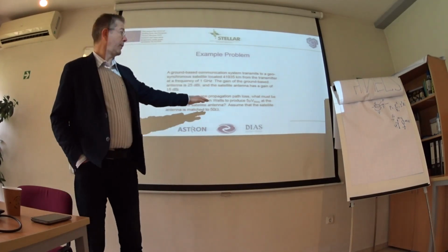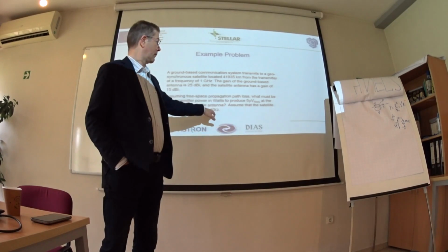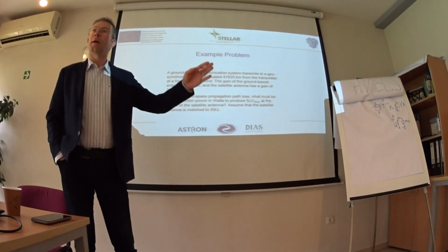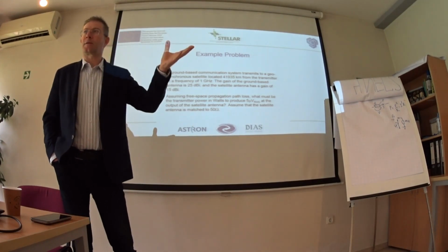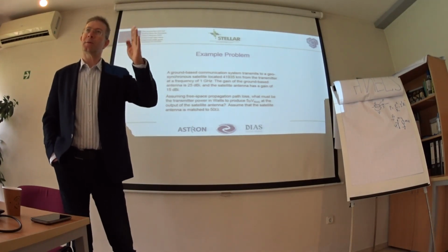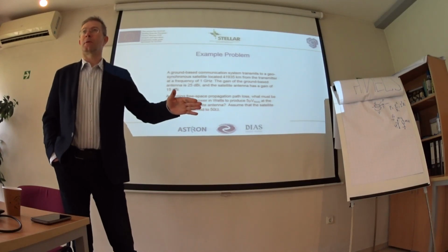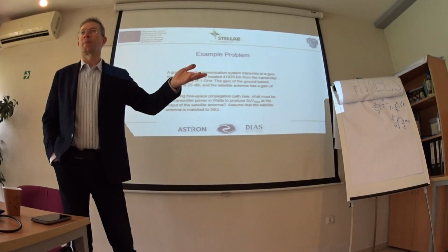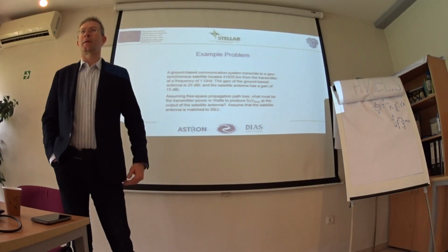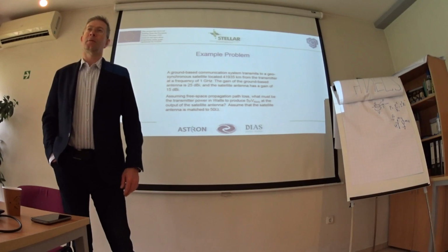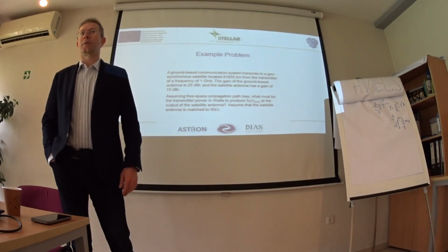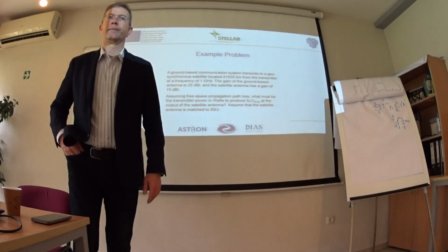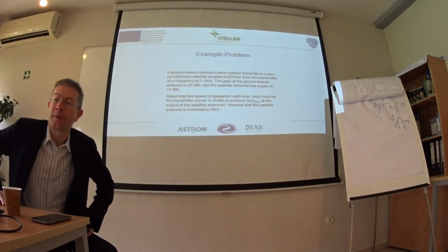And then we divide it by the impedance, 50, and this will be the answer in watts. To convert it to milliwatts, multiply by 1000, and then take 10 times the logarithm of the value. And we receive the power.